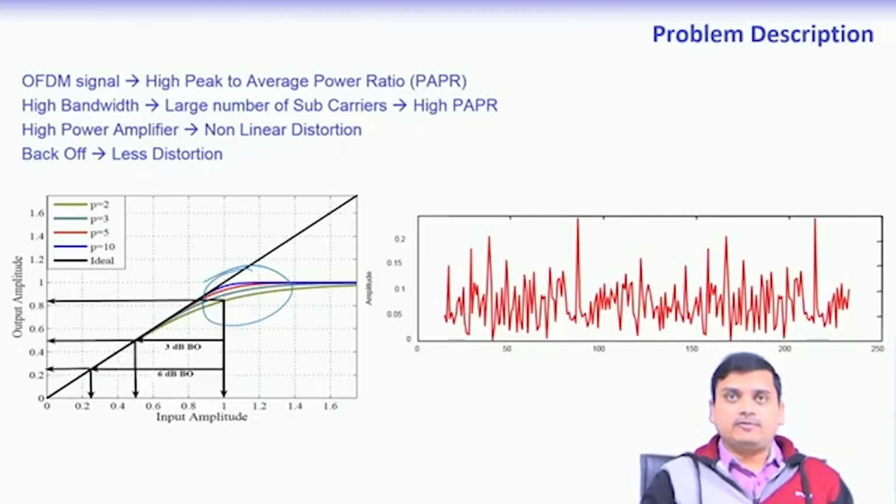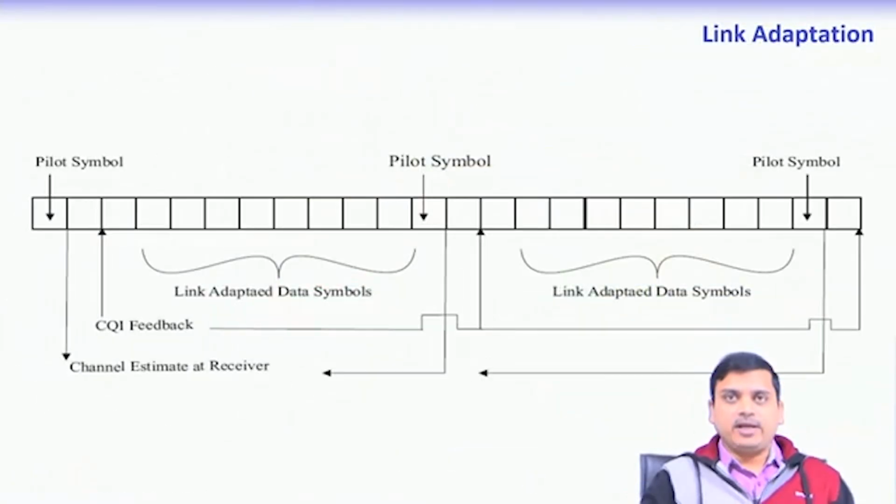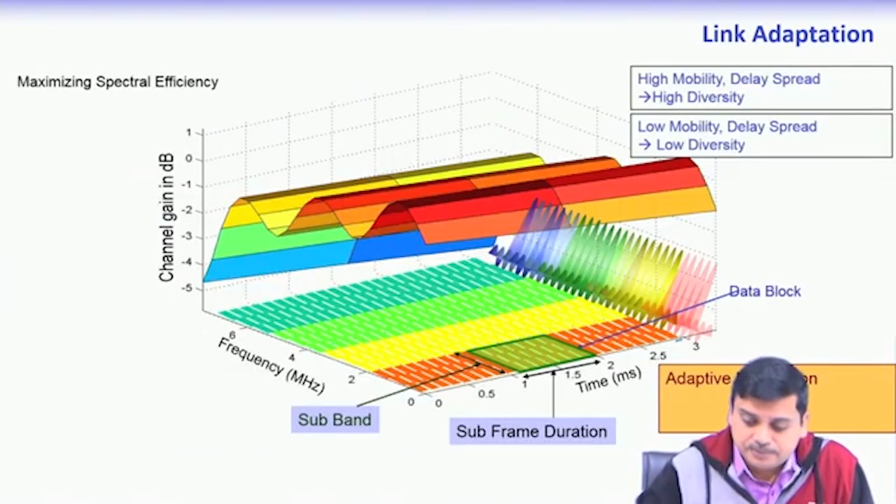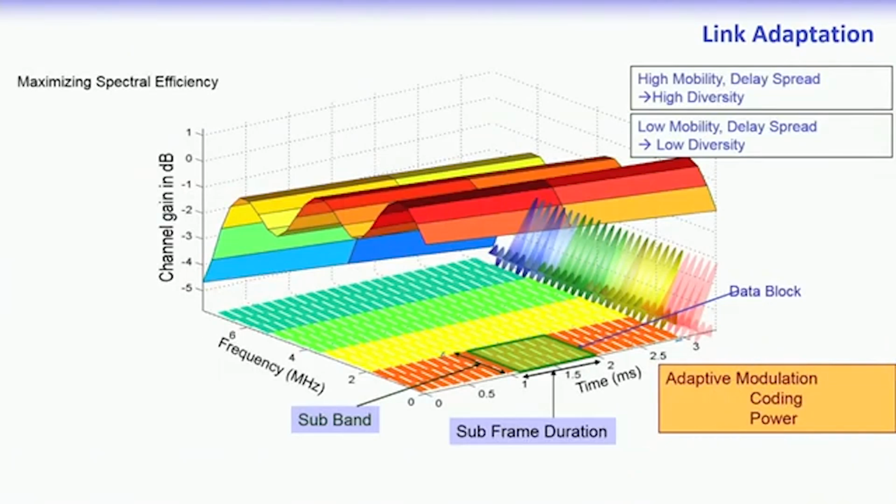Now, another way of seeing it, let's carefully take a look at that. If one of the users is being allocated only one such band of frequencies, right, that means only these few frequencies are going to get non-zero constellation points or symbols. So, for that user, all these other subcarriers would be getting 0 as the symbol value.